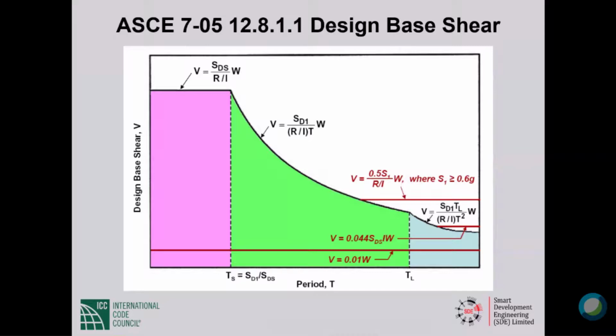We will design a hospital using a special moment frame for an R value of 8 divided by 1.5, okay, which will be 5 and a third. So we will allow less inelastic deformation. That's the idea. Okay, that becomes transparent. So we raise the elastic spectrum by the importance factor I, we lower it by R.